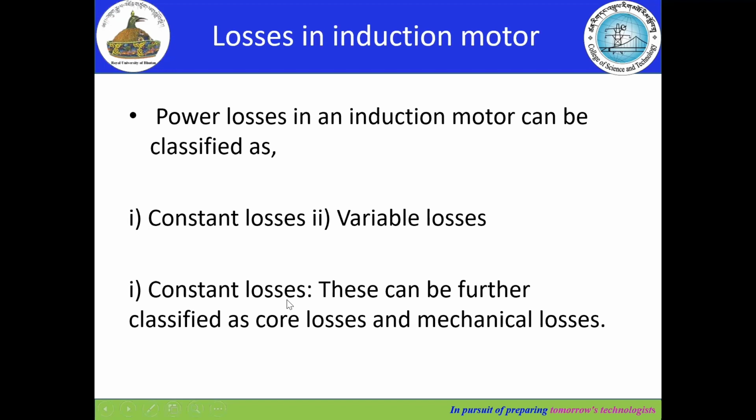Losses in induction motor. As you all know, in an induction motor there will be power losses. These power losses are classified into two: the constant losses and the variable losses. The constant losses are further classified as the core losses and the mechanical losses.